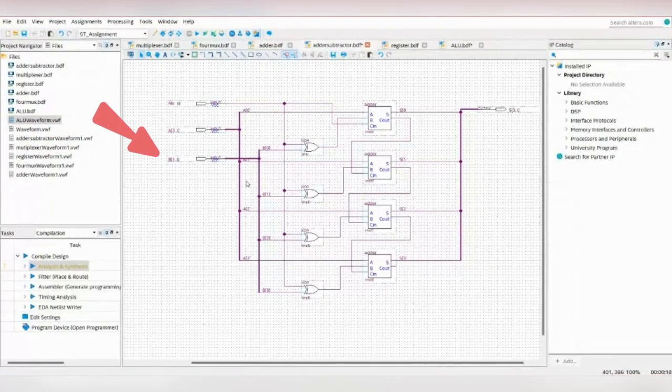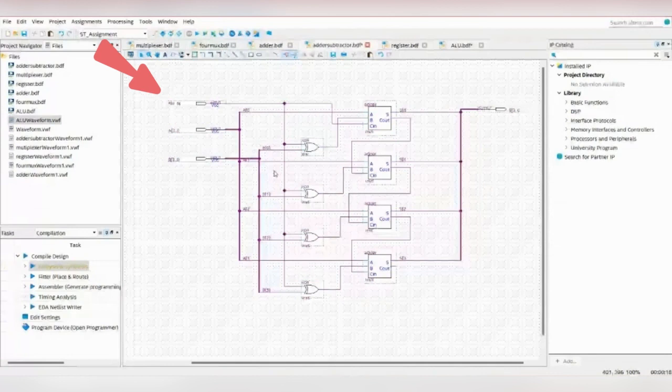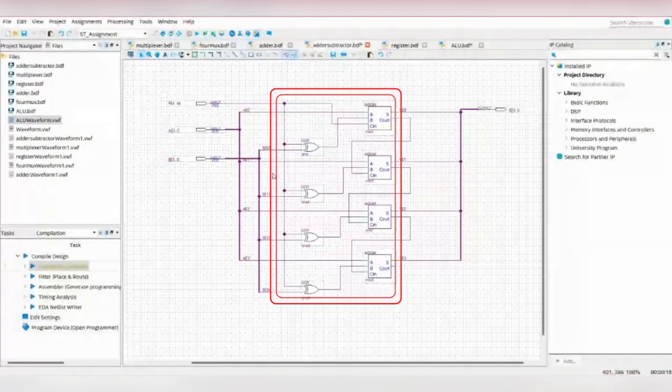For our 4-bit B inputs, we are connecting each of them with a carry-in input through the exclusive OR gate. So when carry-in is 0, this ALU performs addition between A and B. If it's 1, subtraction is performed. Connect the outputs from each exclusive OR gate to the full adder at input B of each adder.